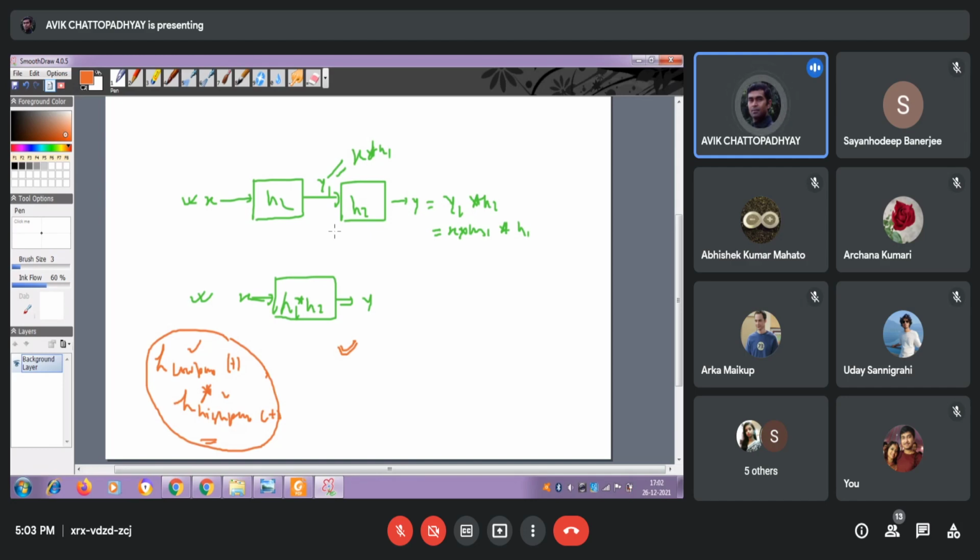There are multiple different types of sources present which can introduce noise in your circuit or system. So you can at least remove some powerful sources of noise, at least by reducing them, because if you implement this individually, then obviously the number of active components will be more, op-amps more, suppose. Here in this implementation, when you club this together by exploiting the associative property of the LTI system, actually it's the associative property of the convolution.